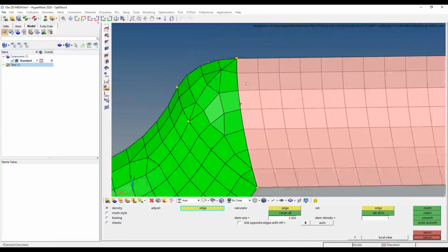So I'm seeing I have 1, 2, 3. Let me get that spotlight tool out. I'm using 1, 2, 3, 4, 5, 6, 7 on the right. That same density of 7 elements carried over immediately to the next surface and the new mesh, 1, 2, 3, 4, 5, 6, and 7. It makes sure that it's repeating those densities in the next surface to ensure that your surface meshes are all going to connect together and tie together correctly at the end.